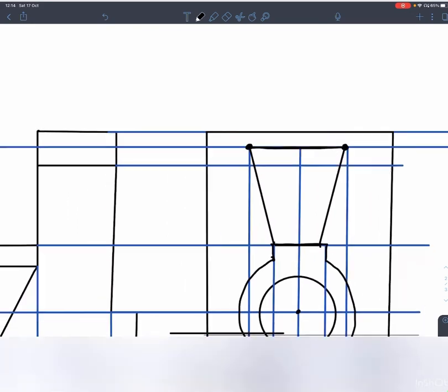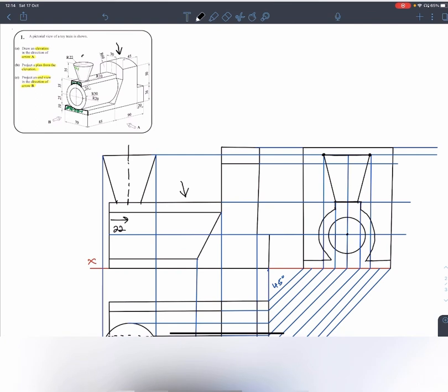So with your compass, we know that it's a radius 60. With your compass, from down this way, from the center line, you're going to mark 60 down. Okay, so we'll say here's 60. So you're going to put the point of your compass on that, and you're going to draw in an arc from the center up until it hits the top like this, and come down again.